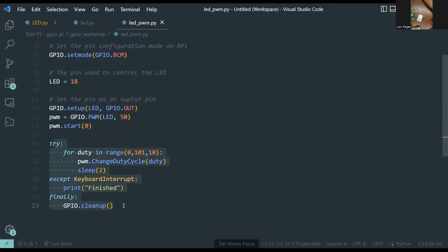Again, you want to wrap everything in a try except finally kind of loop, just making sure that this last function runs whenever you are executing the program and it stops, or when you want it to forcefully stop. You want to make sure that you have this GPIO cleanup thing, just so that, again, it removes any configurations done to the pins that will last outside of the runtime of the program. But let's go into the main logic.